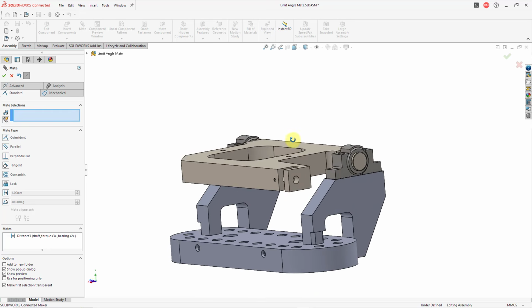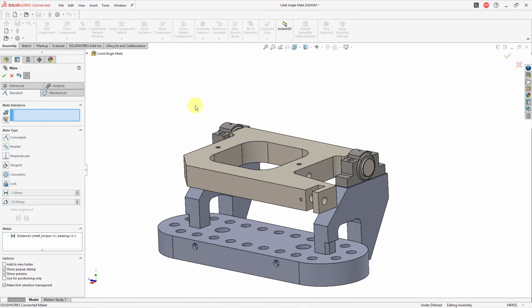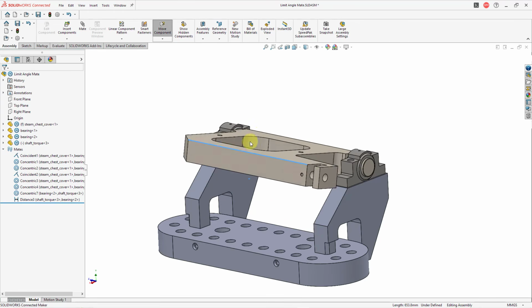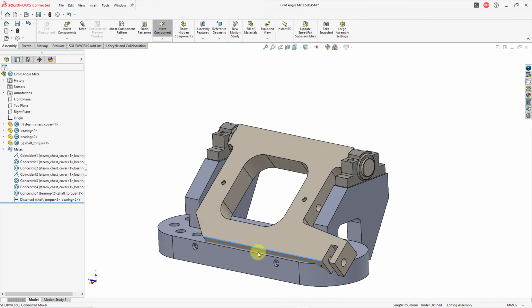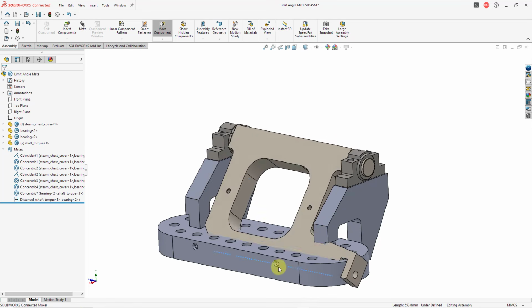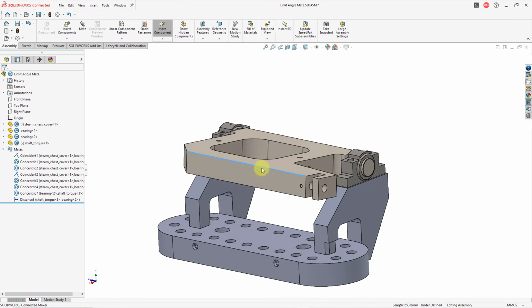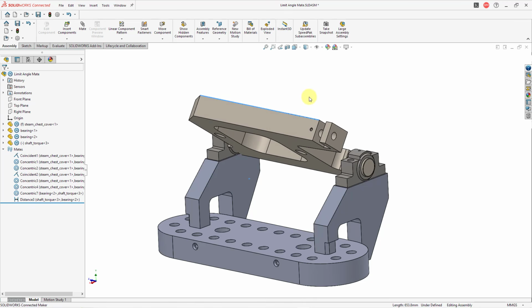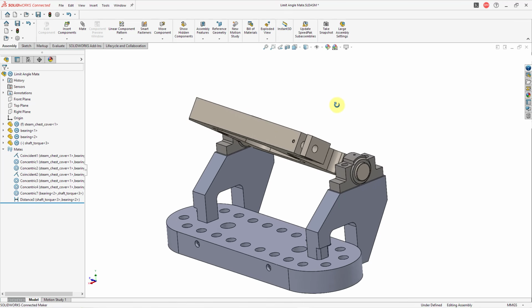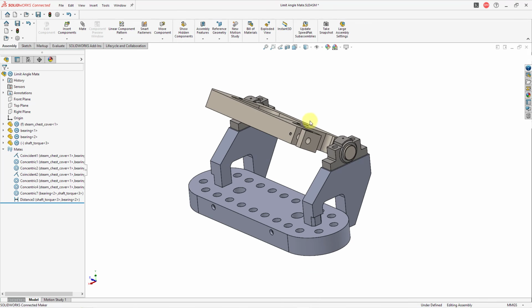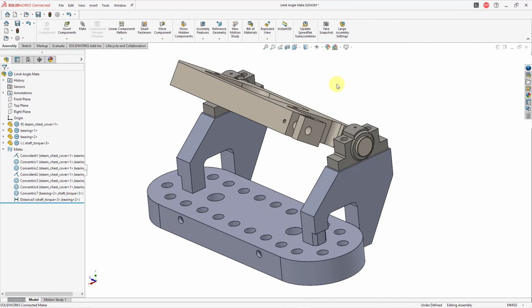And there we can see our component. Once again, I'm going to complete out of creating mates to show you that if I click on this, we have 1 rotational degree of freedom. But you can see that I'm getting collision with the first component in the assembly, and I don't want that. So I want to set limits on the motion. So let's put the component about here. Let me click on the background to deselect everything, and let's set up how I want to look at this.